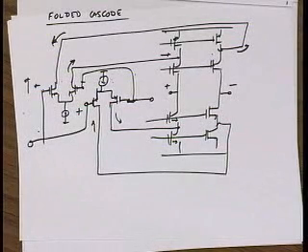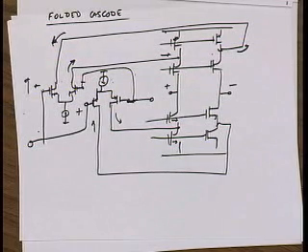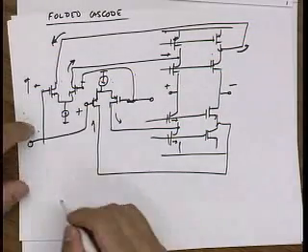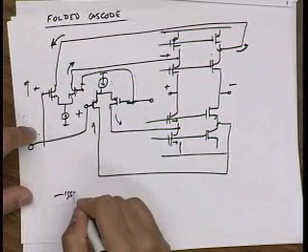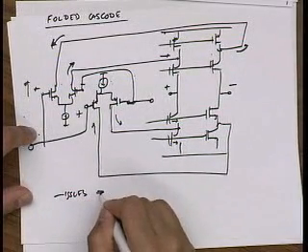Okay. So what are some of the advantages and disadvantages of this over a normal cascode? First thing I'd say is that you lose some phase margin right at the beginning, because the NMOS and the PMOS have two different paths, and one is slower, one is faster, so you lose like 20 to 30 degrees of phase. So yeah, you are right. One of the issues is you get an extra non-dominant pole.